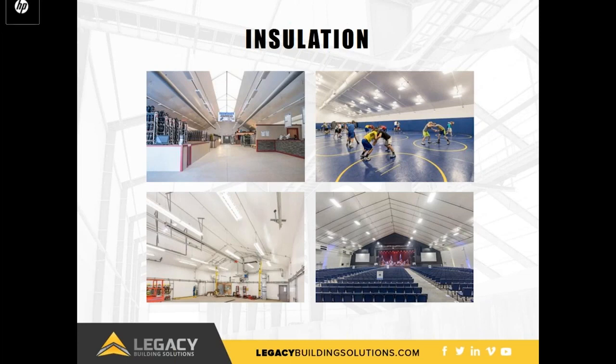Insulated fabric buildings have two big advantages over similar metal buildings. The first is that the fabric liner makes a tight vapor barrier for the building, reducing heating and cooling costs through reduced air leakage. This is a result of a continuous membrane liner, instead of a vapor barrier that is dependent on tape joints to maintain continuity, as in a typical metal building.